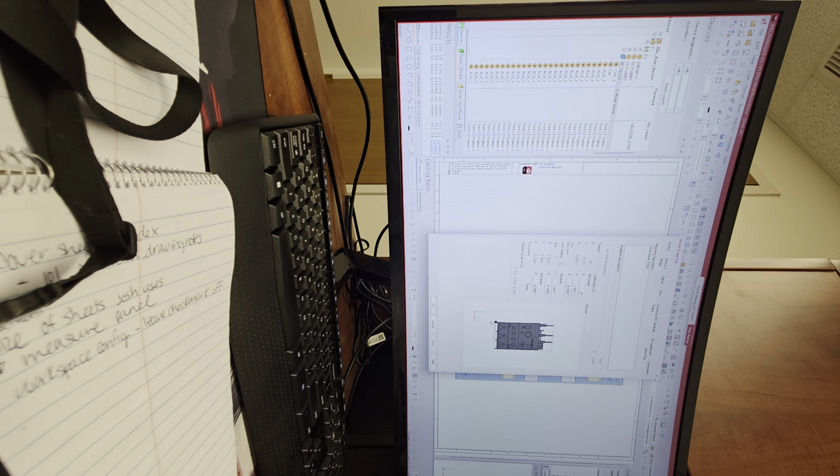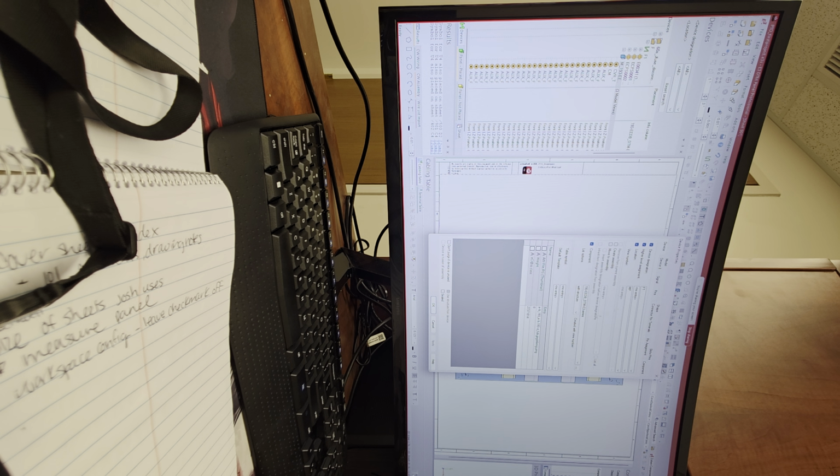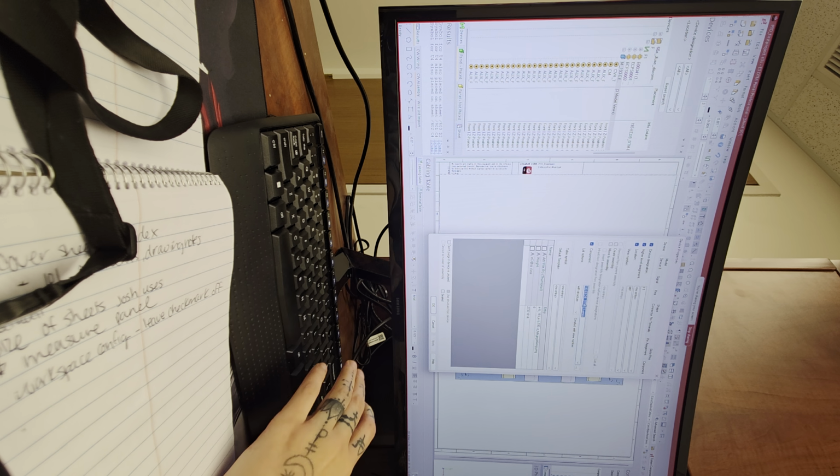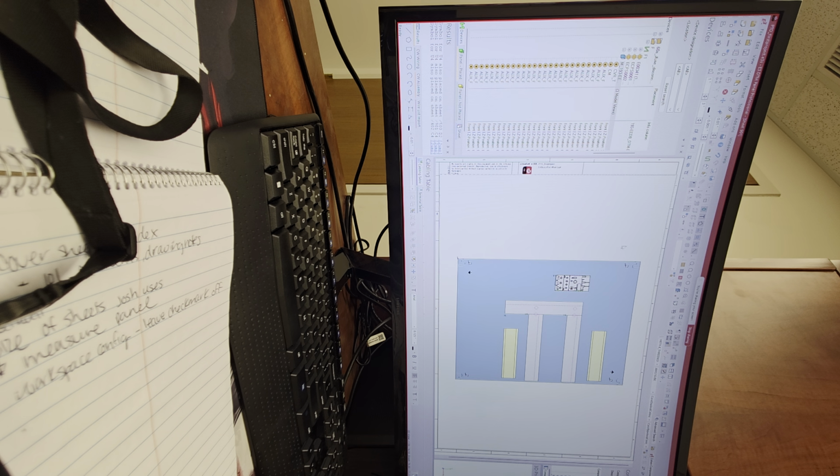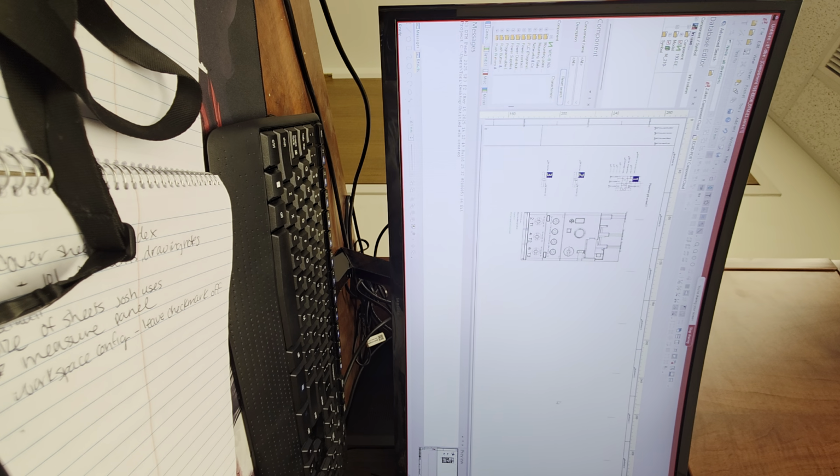So let's see here. To do this quick fix once, click on the Device tab just to grab the part number for this part, so we can delve into it. Under Component, copy that entire 193 number. Okay, Control C, copy it. Cancel out of this. Now we're going to go into our library under Component and search for the component name by pasting it in there. Press Enter. Okay, now one search result. Right click on that and say Edit, and it's going to open up your editor as a default. It's going to take a minute or so to load, because it is opening a separate application.